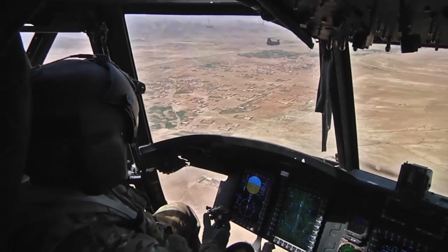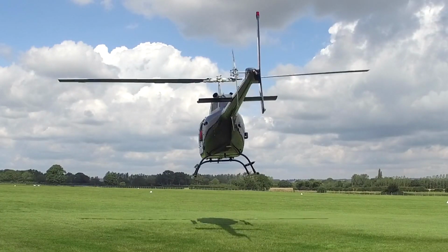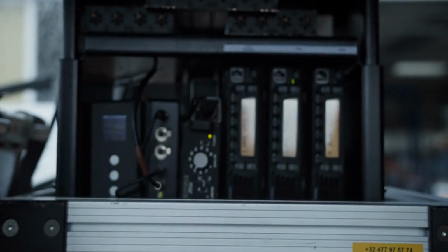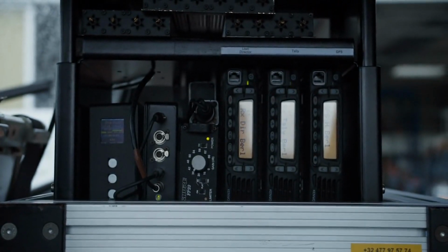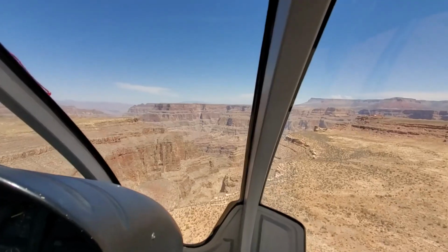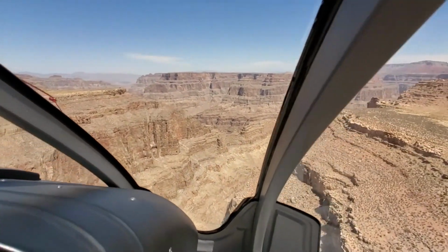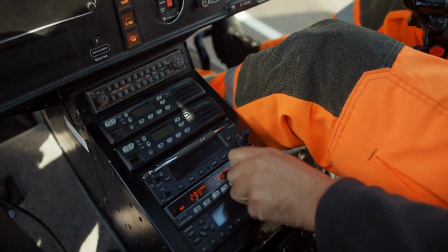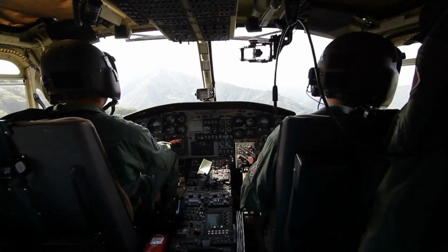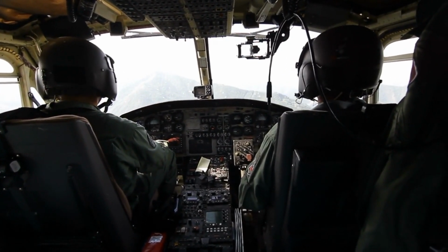As with any maneuver, common errors lurk, waiting to challenge the pilot's finesse. Tenseness and delayed reactions to helicopter movements must be avoided. It's imperative to factor in the inherent lag in cyclic and collective pitch, preventing overcontrolling, a common pitfall for students getting ahead of the helicopter. Confusion between attitude and altitude changes should be evaded, as improper use of controls may result. Hovering at inappropriate heights, either too high or too low, poses significant risks. Pilots must consult the height velocity chart to determine safe skid heights and prevent hazardous conditions.